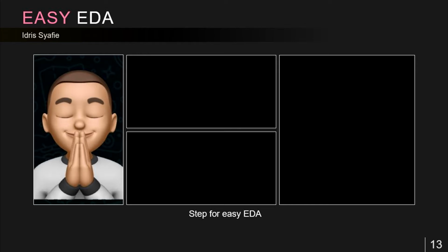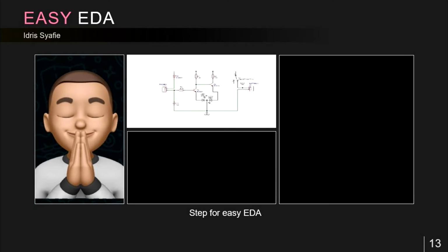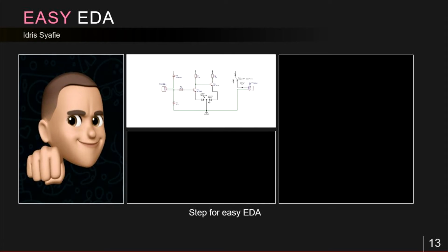Today I am going to present the tutorial to create a PCB based on Figures 1 and 2 using Easy EDA. Firstly, we need to create a new project in Easy EDA. After that, create the schematic design of the circuit. The components can be found in the library, so just take all the components we need from that library. After that, create the wiring in the schematic circuit. Make sure your wiring is correct so there will be no mistakes when creating the PCB. Use the screw terminal in the library for the power supply and input-output terminals.